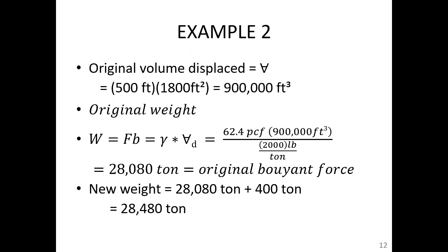And now we're asking how much further does the ship sink into the water? So again, for the next problem, the force equilibrium in the vertical direction, Archimedes' principle still operates unless H is greater than the side of the ship. So if you put on so much weight that you push the side of the ship below the water line, you've sunk that ship, right? So obviously I didn't give you a limit, but for example, let's say we had 5 feet above the water line. And we're going to calculate H, and what we're going to hope is that at 400 tons, we don't sink the ship more than 5 feet.